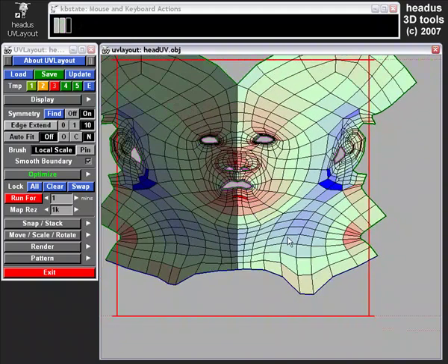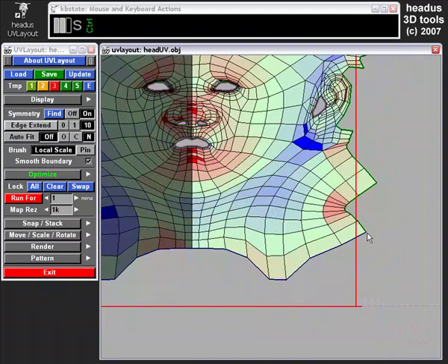So that's what I'll do now: pull this point down here and set an anchor there, which means that when I move these other points, they'll snap vertically, and this one here will snap horizontally to that anchor point.